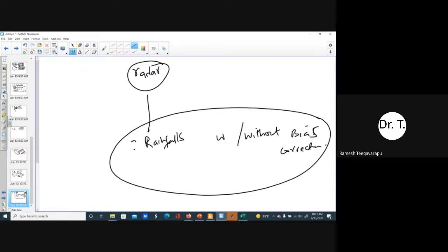So you can use IMD data sets to see how well your reflectivity values are capturing in the past. If you have, let's say, past years' reflectivity values, you can check how well the IMD gridded data product compares with the radar-based precipitation estimates you are generating. And of course, if you have rain gauges in that area, you can also do some bias correction of the reflectivity-based rainfall estimates, and then check how well you are doing with respect to the gridded IMD data. You can do that.